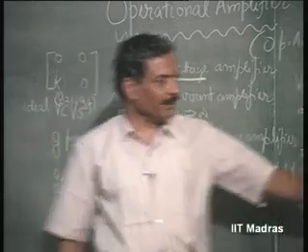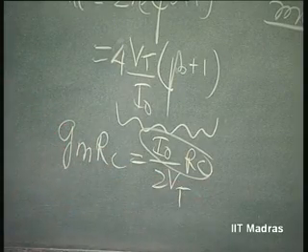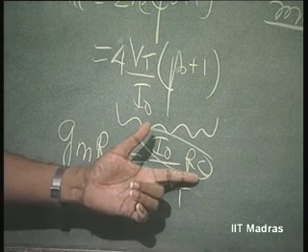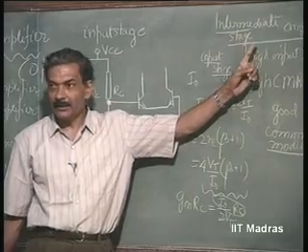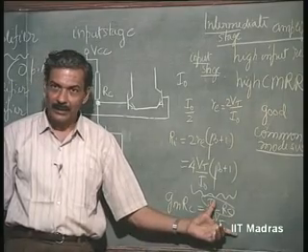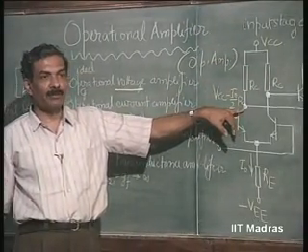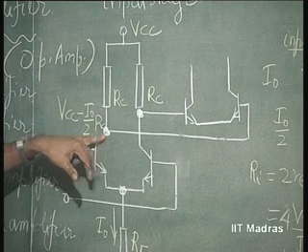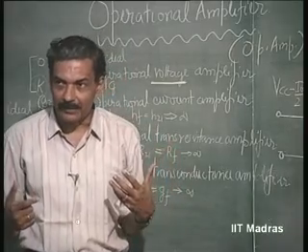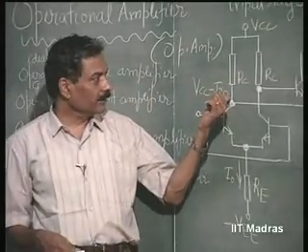So, we cannot make this too low, right, because the gain decreases considerably. Now, consider this: I naught into RC can be maintained at whatever level you want. When I naught is reduced for the sake of increasing the input impedance, RC can be increased, making I naught into RC high. But the moment I naught into RC is made high, the common mode voltage capability goes down. Now, how to tackle this? This was a major problem in the initial stages of op amp design. Then they solved this by a very intelligent technique.